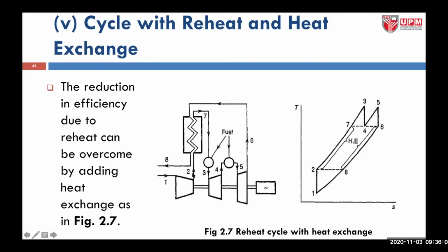So we put back the heat exchanger in the system, where just after the compressor we introduce a heat exchanger. Before it, we have the combustion chamber, and we have the turbine, we have another combustion chamber, and we have the power turbine.